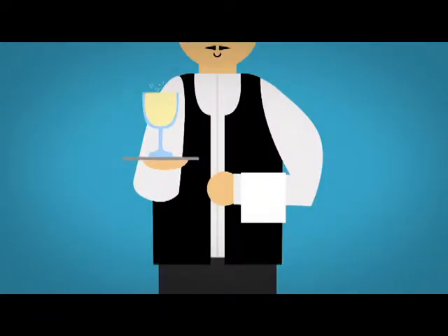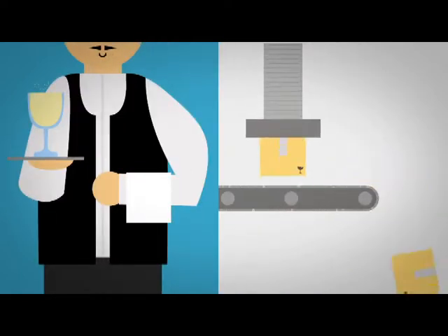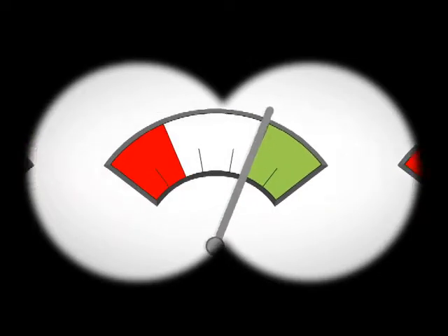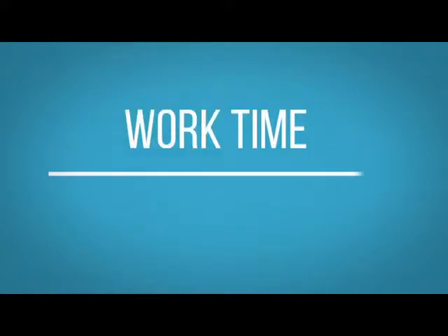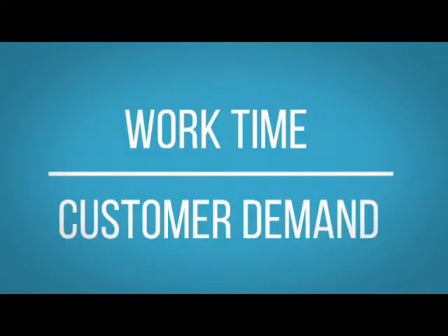Step 6. Determine the takt time. Takt time is the rate the customer uses the product, which leads to the rate the plant needs to catch up with the customer demand. It is calculated by dividing the available work time by the customer demand.